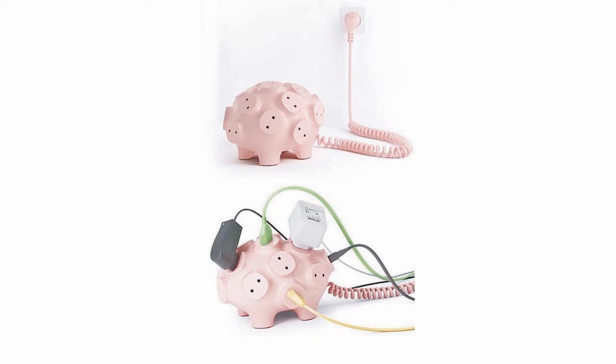Today's topic will be on product design with Modo and Meshfusion. I love Meshfusion's flexibility. It allows me the flexibility of subdivision modeling with the Boolean operations and those smooth fillets of cut packages. It allows quick concept modeling without having to worry about any topology issues. Depending on your case, you can use Meshfusion from beginning to end of your project, or you can also use Meshfusion as a quick way to create some geometry that you then retopo later with Modo.